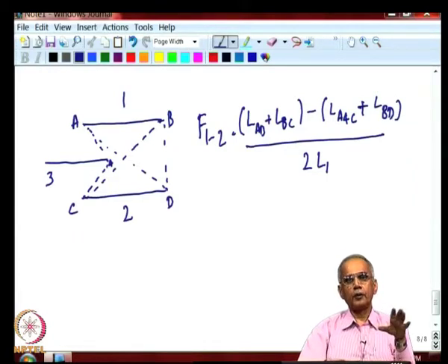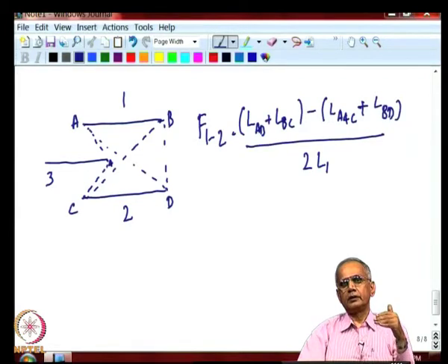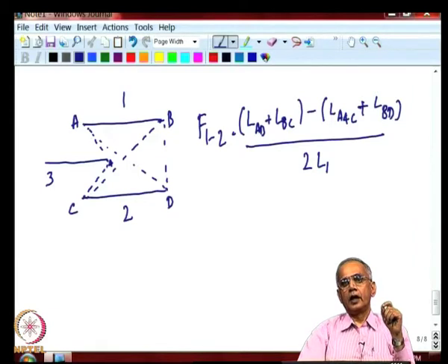So, after drawing your parallel strings and cross strings, draw a few rays, extreme ones especially, to see whether the parallel strings do not allow radiation which should reach 2 to leak through, and the cross strings are such that every ray which leaves 1 and arrives at 2 does cross both cross strings.